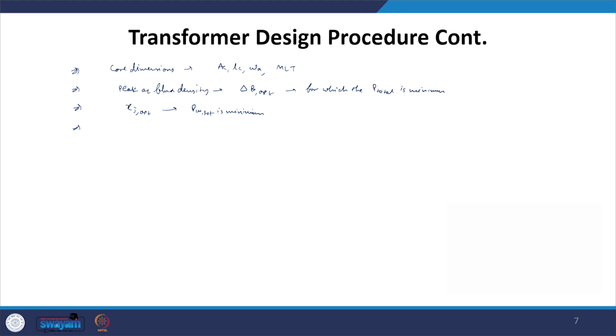Then after that we have got our AW1, our AW2, that means the area of cross section of wires, and AWK. We have got the number of turns N1, N2, N3 up to Nk, and using these particular things we will be in a position to now physically realize our transformer.